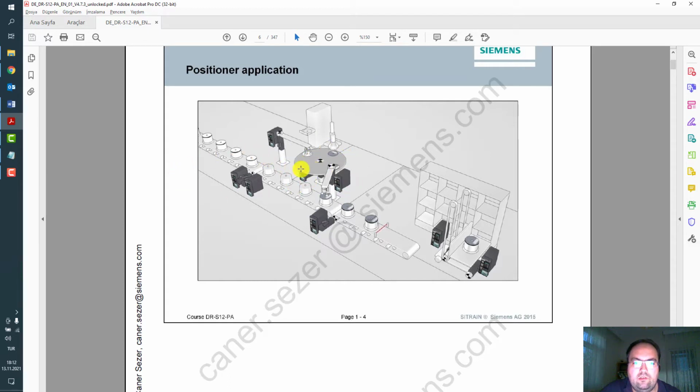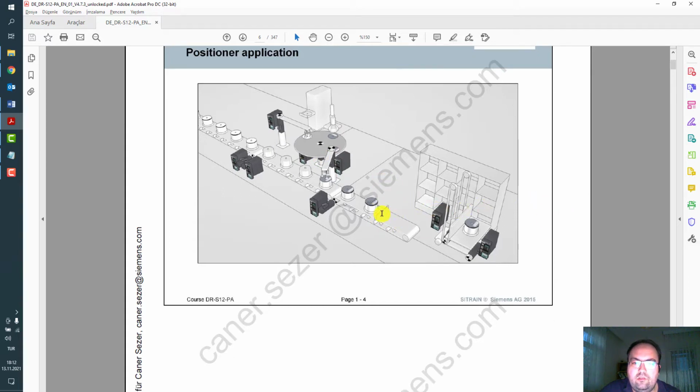There are some functions and there's a sensor for print mark correction or creating a new product running on belt for positioning or passive homing. There are two axes like X and Z for destacking and stacker system. Works together, two axes MDI positioning, for example.